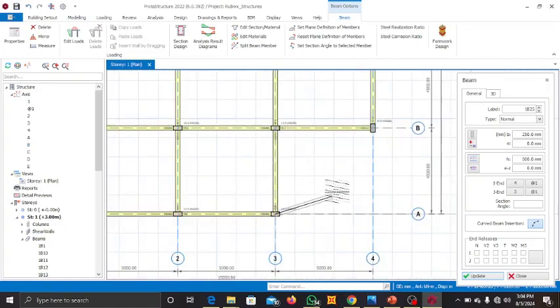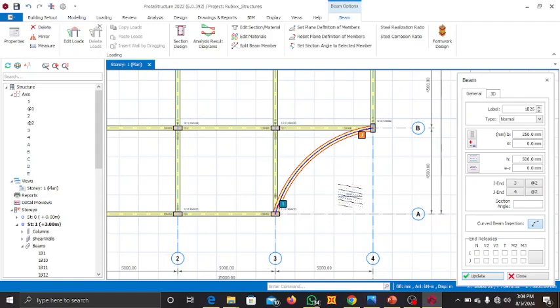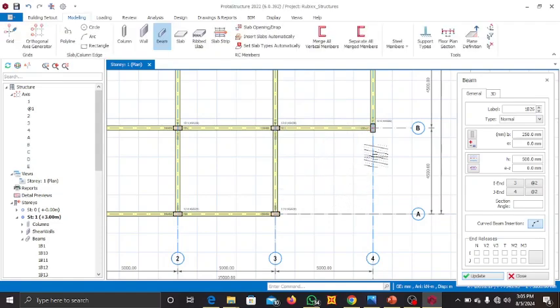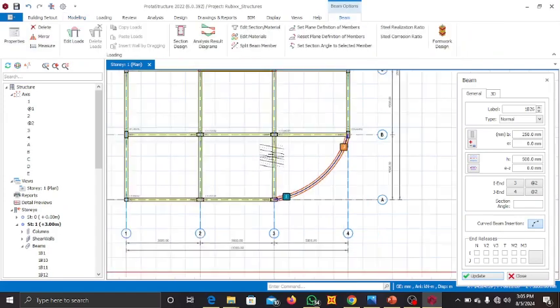You can do same here. Pick this, pick the second point, you hover inside the position you want it to go. F2, 1000, you press enter. Oh, sorry, let's delete that and do it again. Press delete, do it again. Fix it at the first point, pick that second point, you hover into it. Okay, so F2, 1000. Okay, now you've gotten that.